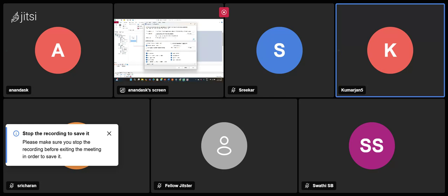So basically, I try to take those logs and put them into different tools. There are so many other tools like INCA. INCA is the one tool which tries to create those system variables which are compatible with any CAN DBC file, and examine those readings, how it is working, and check that those values are within the permissible limit.